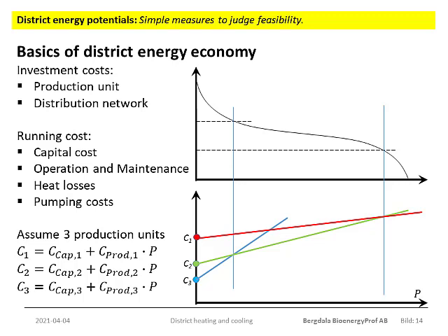The production costs are composed of a capital cost, which is constant, and a total operational cost, which is constant as per power unit produced. So we multiply the specific cost with the power produced to get the operational cost. The lower diagram now shows the total production cost for each of the 3 units. And as you will see, the blue curve for unit 3 is the one with the lowest total cost for smaller amounts of energy. Do not mix this up now.